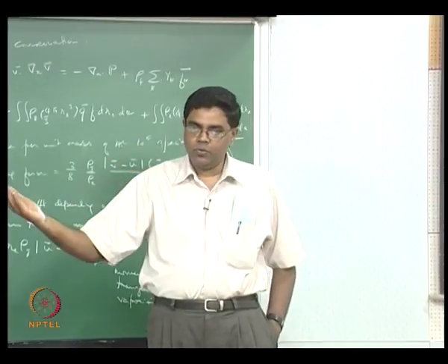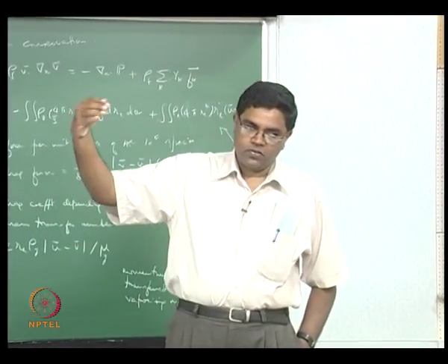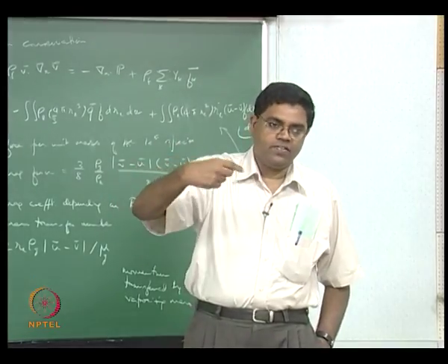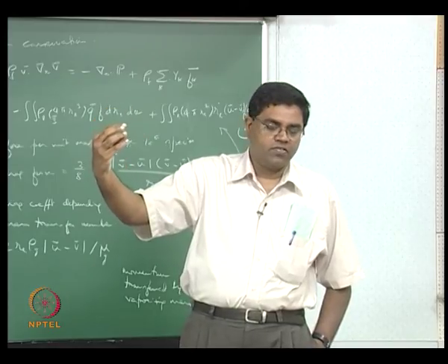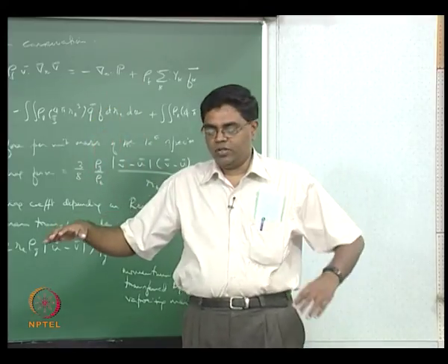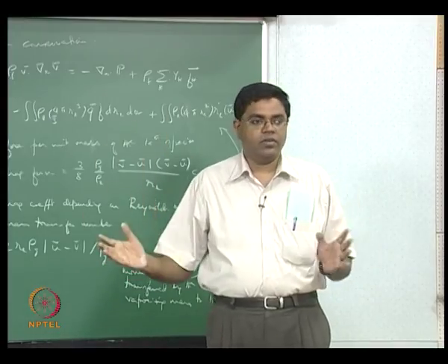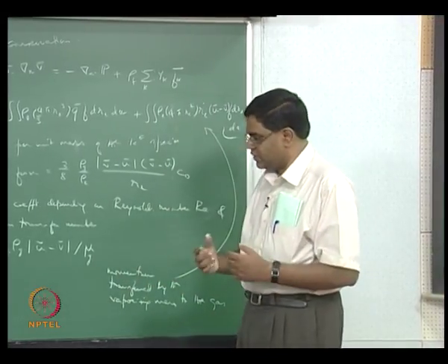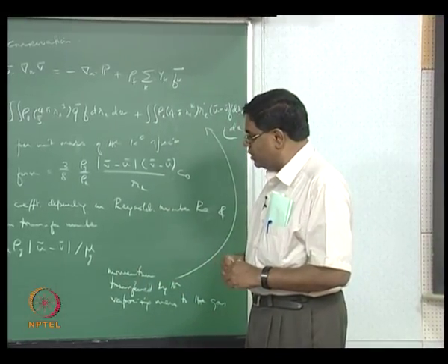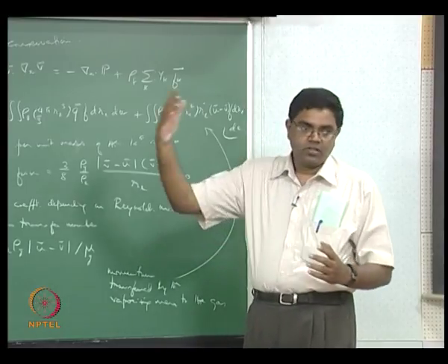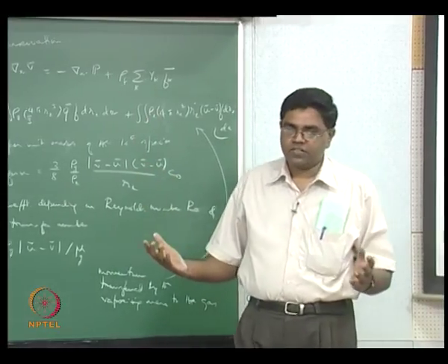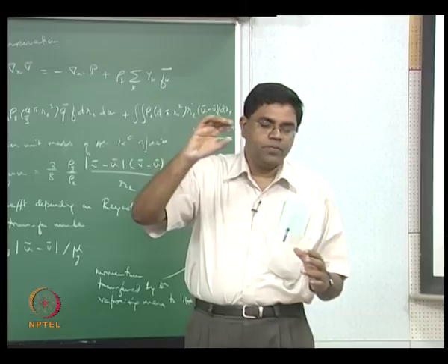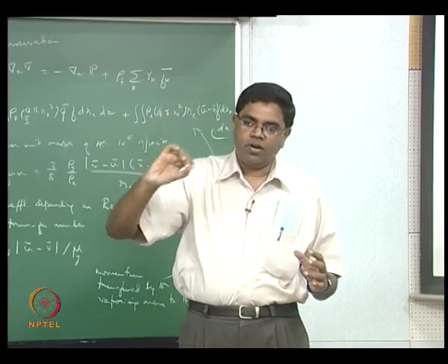So you now have an overall turbulent field into which the droplet is moving, following the turbulent flow around, but as it is moving it is also producing a wake behind it, and this wake is obviously of length scale of the order of the droplet size rather than that of the characteristic dimensions of your combustor or your burner, which the overall prevailing turbulence is of a length scale of. So what happens is, you now have these multiple length scales of turbulence, the larger length scale corresponding to the combustor geometry and the small length scales of the wake turbulence from these droplets.